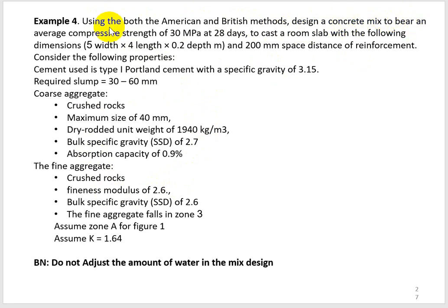a concrete mix to bear an average compressive strength of 30 megapascal at 28 days to cast a room slab with the following dimension, the same dimension as we have in the previous examples. Also we have one of the quizzes that has the same dimensions, and 200 millimeter space distance of reinforcement, and consider the following properties.